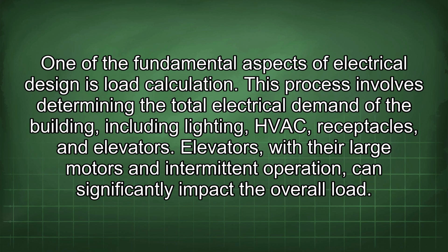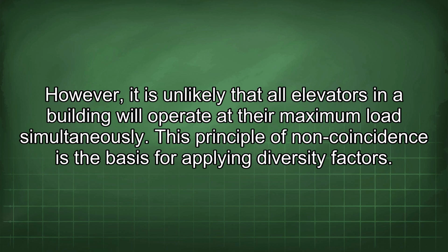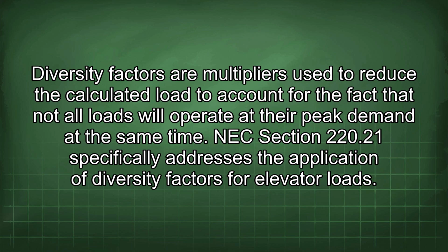One of the fundamental aspects of electrical design is load calculation. This process involves determining the total electrical demand of the building, including lighting, HVAC, receptacles, and elevators. Elevators, with their large motors and intermittent operation, can significantly impact the overall load. However, it is unlikely that all elevators in a building will operate at their maximum load simultaneously. This principle of non-coincidence is the basis for applying diversity factors. Diversity factors are multipliers used to reduce the calculated load to account for the fact that not all loads will operate at their peak demand at the same time.